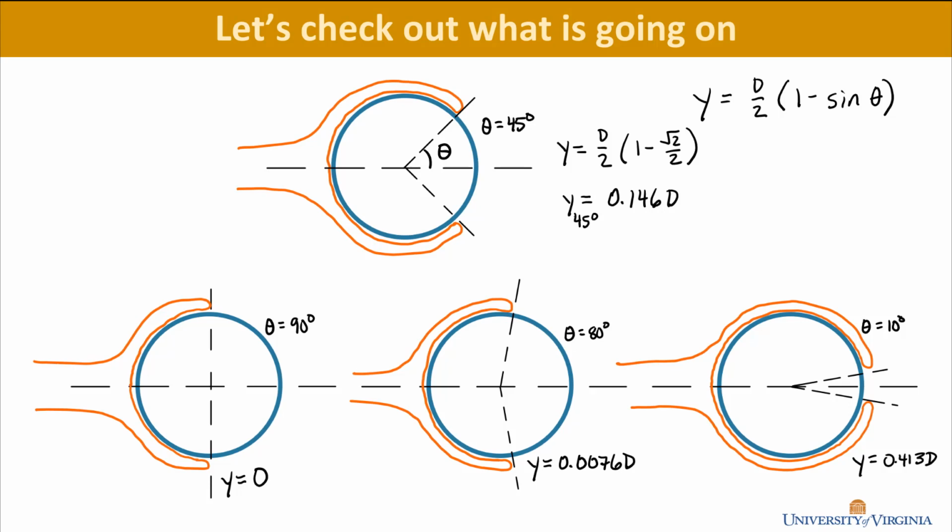And interestingly, as you progress from a snap at theta equals 90 degrees, which really isn't a snap at all, it just kind of pushes up against. But as you start decreasing theta, so you have more and more material wrapping around this rod, for every degree that you keep reducing for theta, initially the deflection changes very small, but for every degree additional that you wrap around your snap fits, the deflection is going to increase more and more and more as you get down further and further.